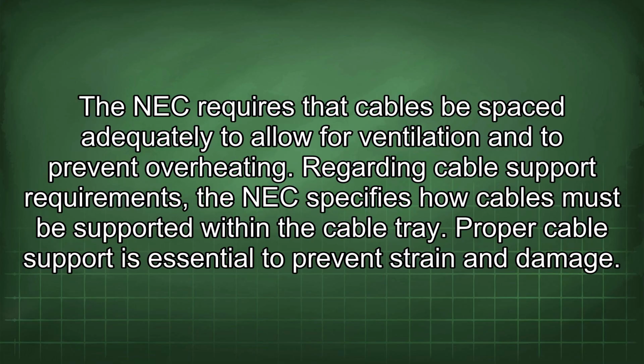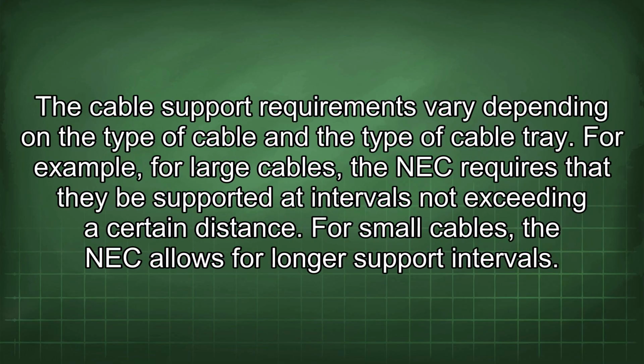Proper cable support is essential to prevent strain and damage. The cable support requirements vary depending on the type of cable and the type of cable tray. For example, for large cables, the NEC requires that they be supported at intervals not exceeding a certain distance. For small cables, the NEC allows for longer support intervals.